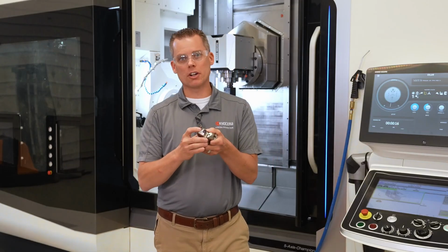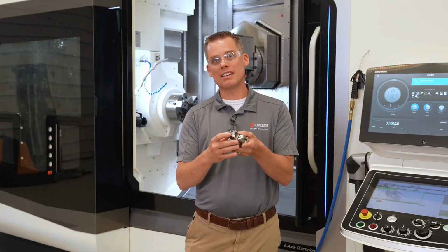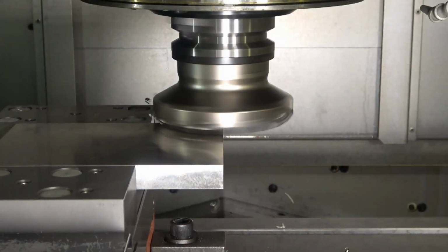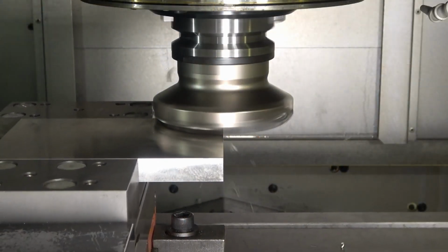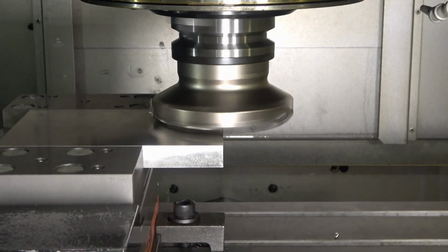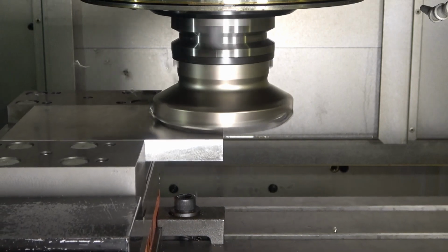While this 45 degree cutter is going to be our best option out of these three for general purpose facing operations, it will not be the best option for reaching close to fixtures or areas where a 90 degree cutter or a high feed mill would make more sense.